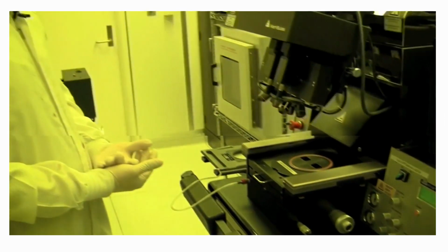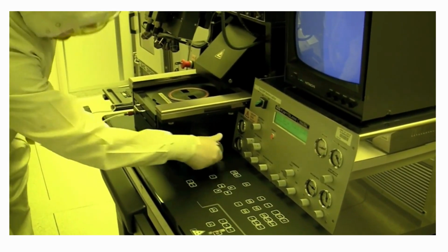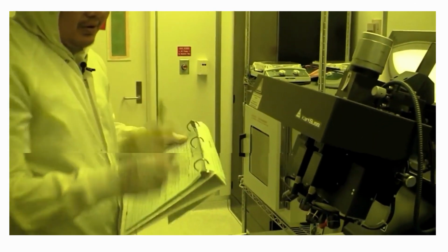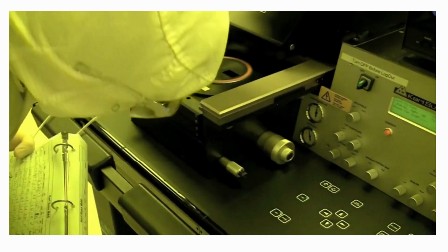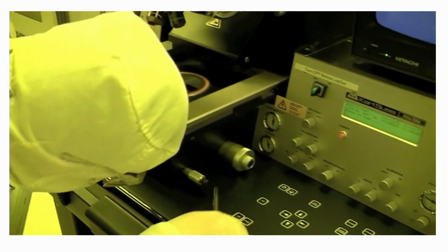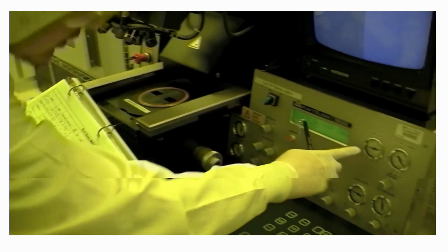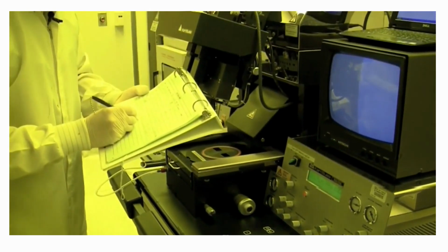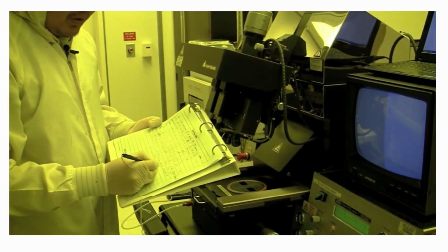So now we're ready to turn the system off. We want to make sure everything's in the standby position that you started the machine with. And then before you turn it off, you want to make sure you write in the logbook the different parameters. The compressed air is about 4.9. The nitrogen is about 1.65. The vacuum is about negative 0.86. We used a 4-inch silicon wafer, and we did a 25-second exposure.